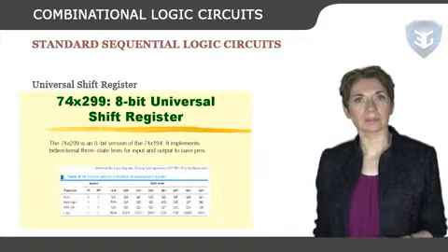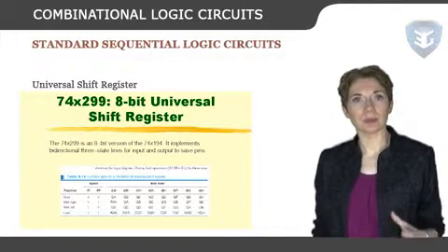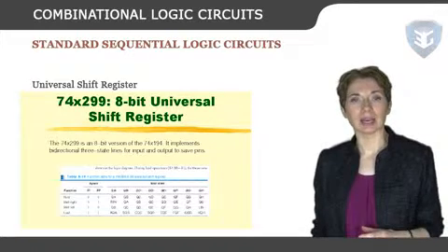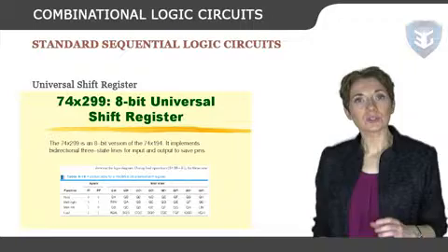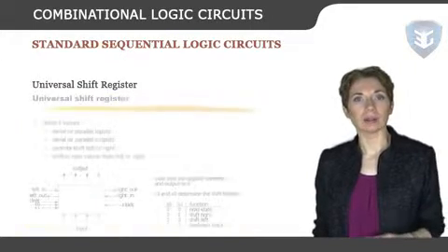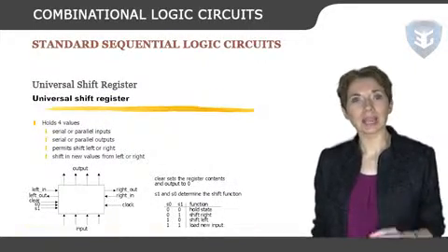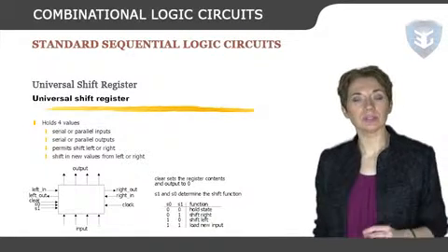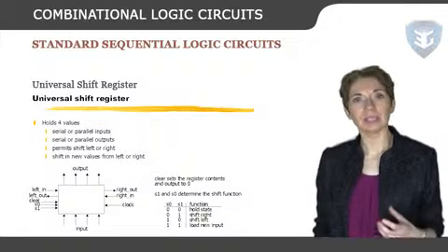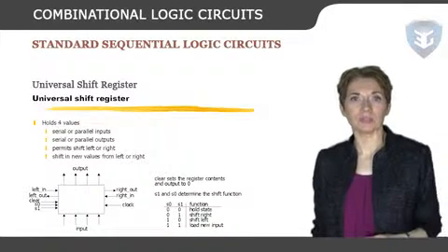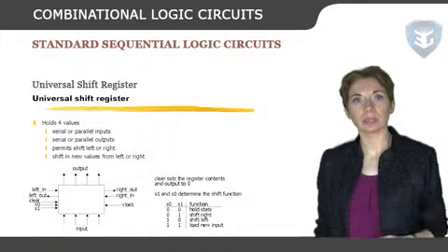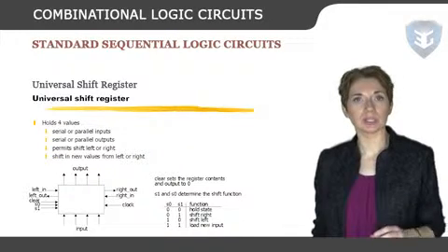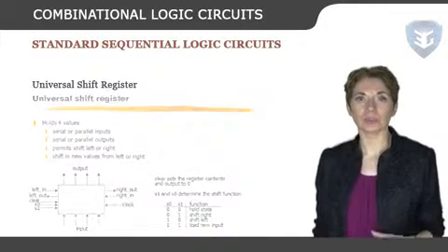Universal shift register. Today, there are many high-speed bidirectional universal type shift registers available, such as the TTL 74LS194, 74LS195, or the CMOS 4035, available as 4-bit multifunction devices that can be used in serial to serial left shifting, right shifting, serial to parallel, parallel to serial, and as a parallel to parallel multifunction data register, hence the name universal.